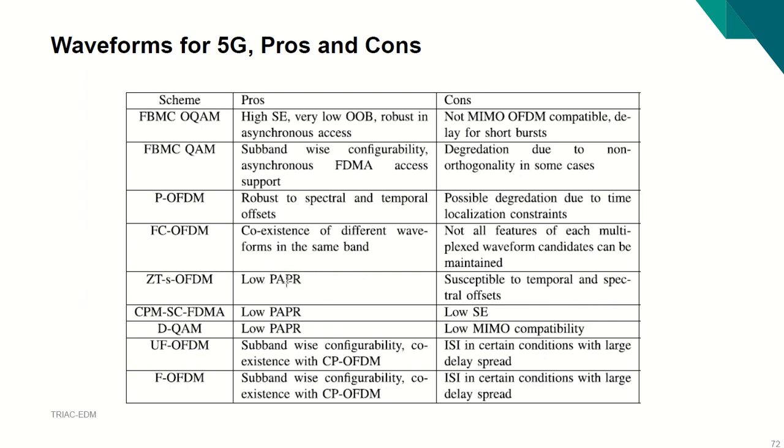We like things to have low PAPR. The reason is that when PAPR is high, it gives us problems in which the amplifier goes into the nonlinear region. The issue is that your peak is very high with respect to average signal strength.